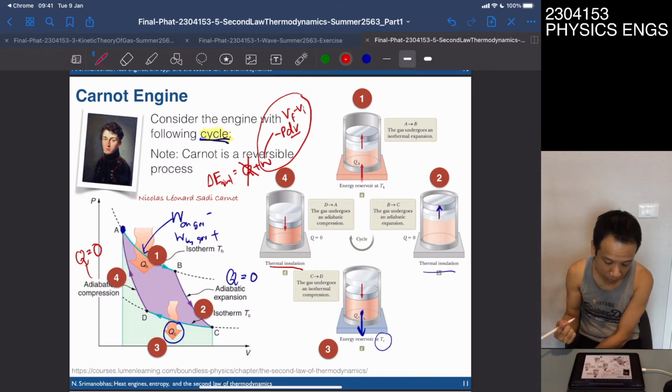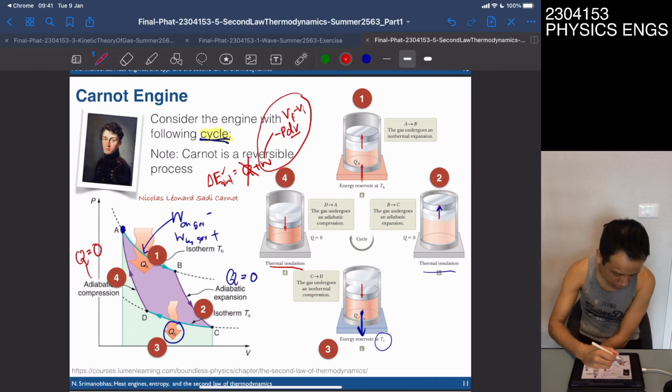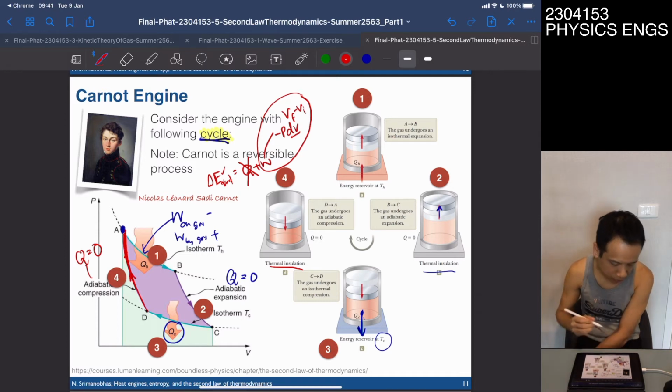So this is work done on the gas, so you need to have the work done on the gas to make its compression, so that you need to increase the internal energies, okay. So that's why it moves along the line back to the hotter temperature lines, okay.